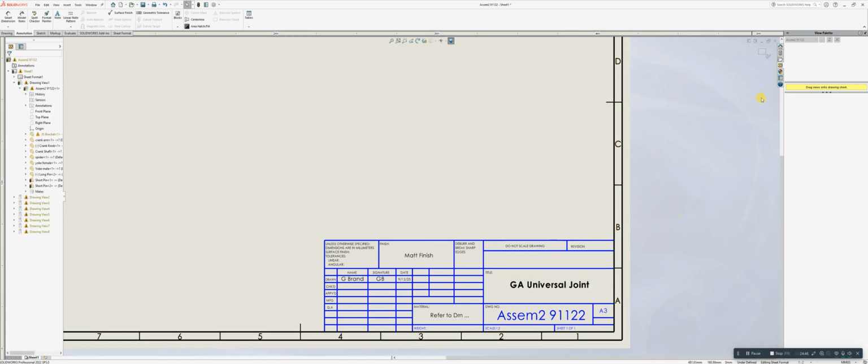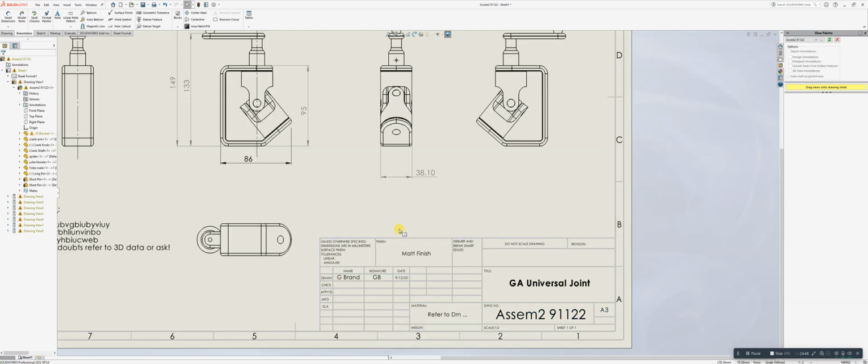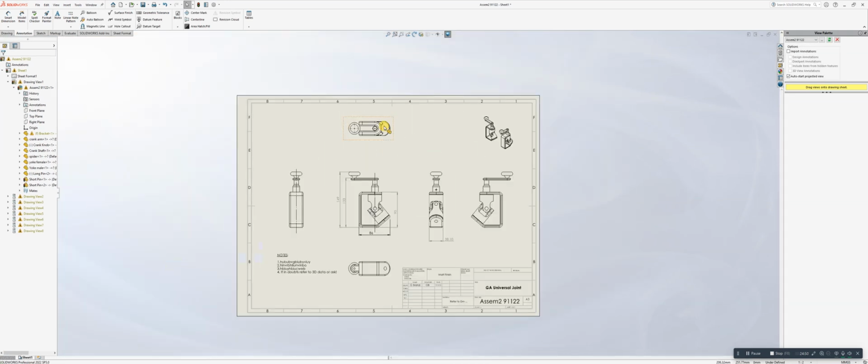Okay, that is the very, very basics of laying out a general arrangement drawing. There should ideally also be the third angle projection symbol put in, but actually the layout is third angle, so don't worry about that for the time being. We can operate that later on. In the next video I'll go on to actually doing a component drawing for that, because there's a little bit more detail to that, but the principle is the same. Good.